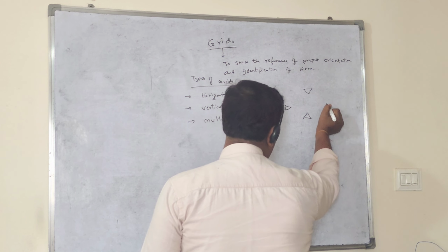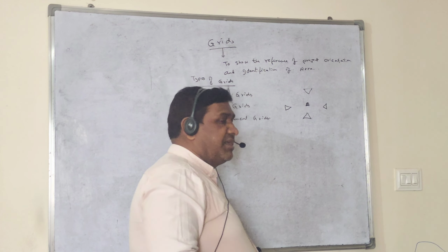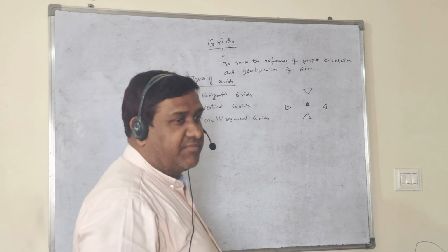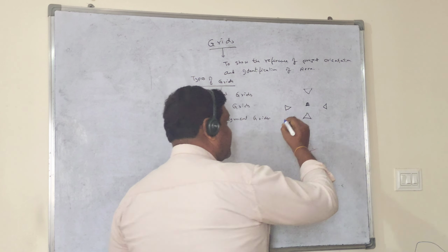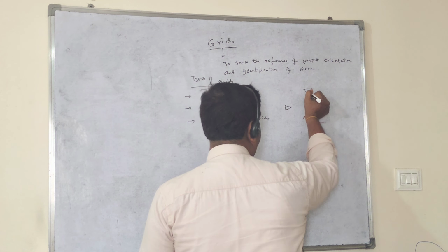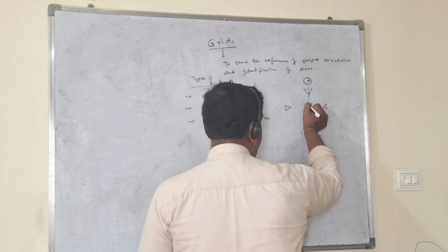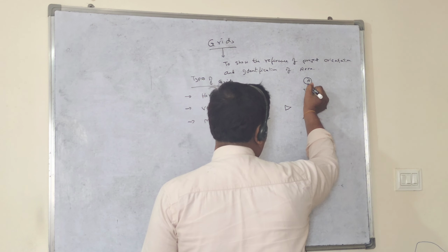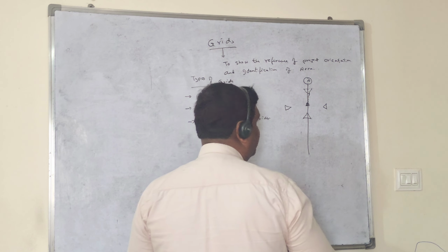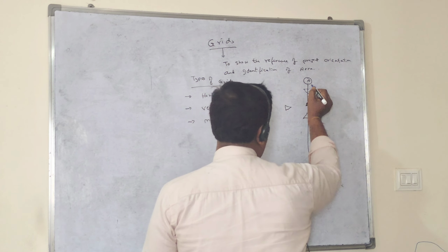Here in the center you have placed the base point, project base point, and survey point. Am I right? This center point is where you have to place the grid. So the grid will become vertically A, and like that the grids will go. Exactly, it will become the center of that project base point and elevation point.